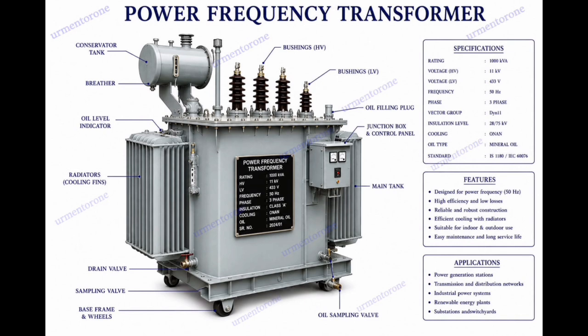It is mainly applicable in step-up and step-down transformers in electrical grids, distribution lines, and industrial power supplies. Main characteristics of power frequency transformers: they are physically large and heavy because lower frequencies require a large core cross-sectional area to handle the magnetic flux without saturating.